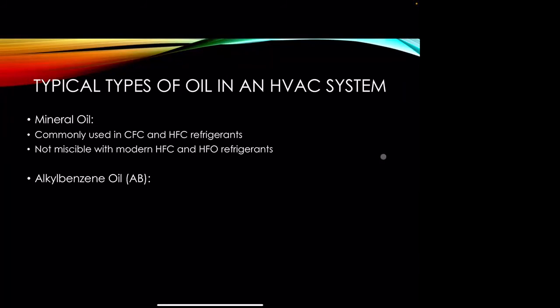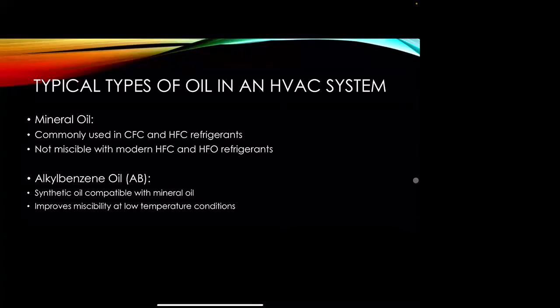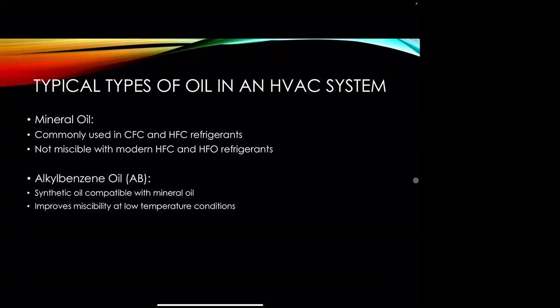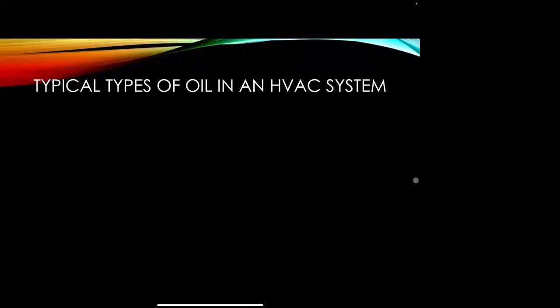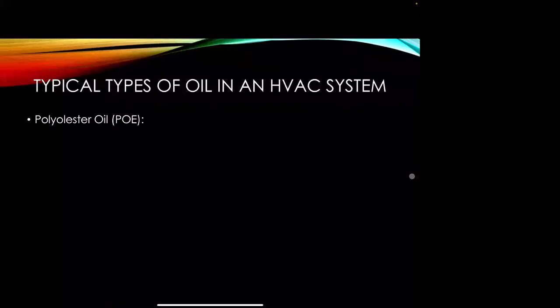Alkyl benzene oil. We're not going to see much of this. This is a synthetic oil compatible with mineral oil. It improves miscibility at low temperature conditions. Our next oil is polyol ester oil, or POE oil. What kind of refrigerant is POE oil in?